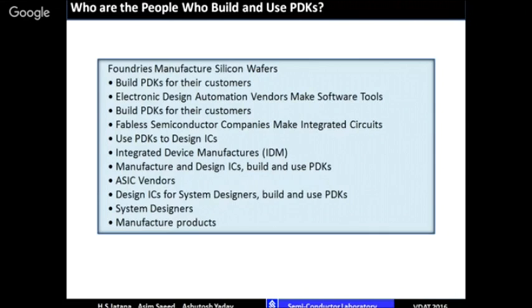So PDKs are made for the designers. It has a PDK specific for a design flow on a particular design tool, like whether you are using Synopsys or Cadence. So your technology files have to be compatible with those design tools.